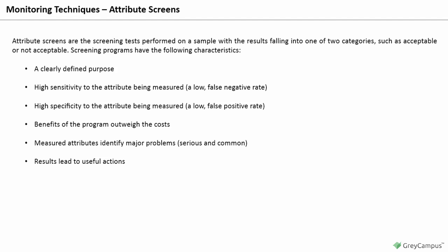The test simulates a customer use of the unit, or perhaps an accelerated condition of use. The number of failures per unit of time is monitored, and the screen test continues until the failure rate has reached an acceptable level. The screen test separates acceptable items from failed items, and an analysis of the failed components is performed to find the cause of the failure.